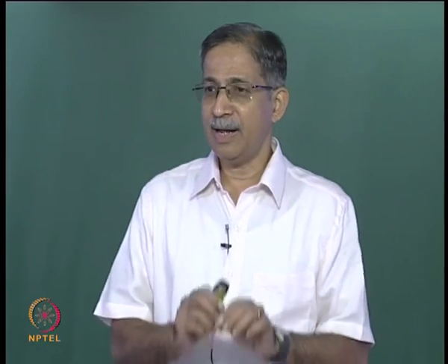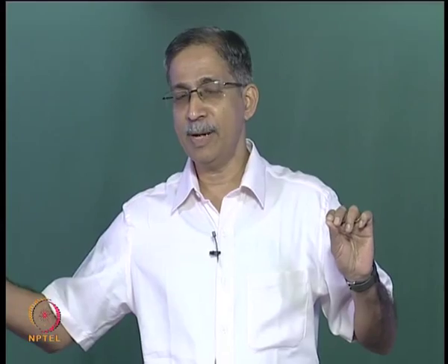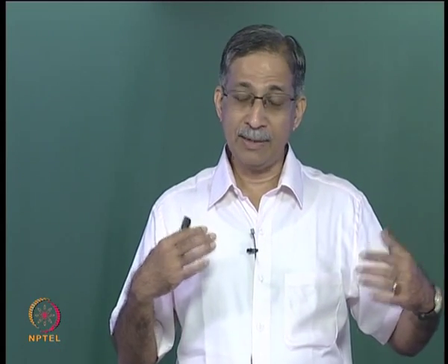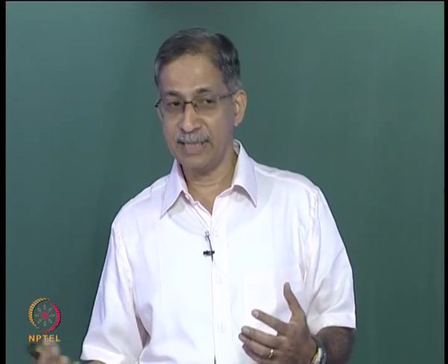What's our objective? We are trying to find a solution to a problem where we can deal with only joint loads. So we want to find the net load vector, and also we want to find the fixed end forces which accumulate at the restraint coordinates.